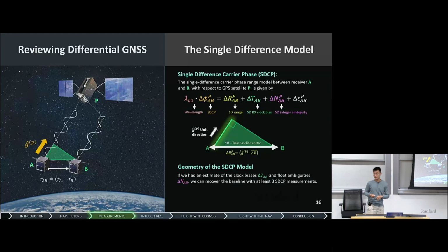But there's not just one GPS satellite in space. You're receiving from 10, 12 GPS satellites. And so what happens is you can group all of these measurements. Let's say you have 10 GPS satellites in view and you've communicated 10 measurements across each other, you can group your geometry terms on the right side and your observations minus uncertainty sources on the left side. Is it your left? Yes, it's your left.